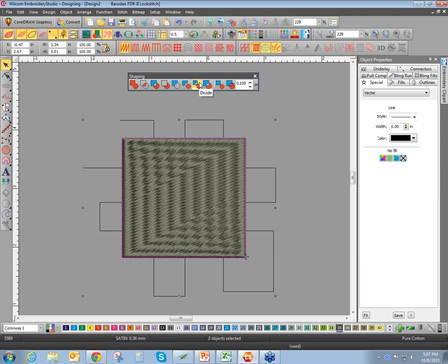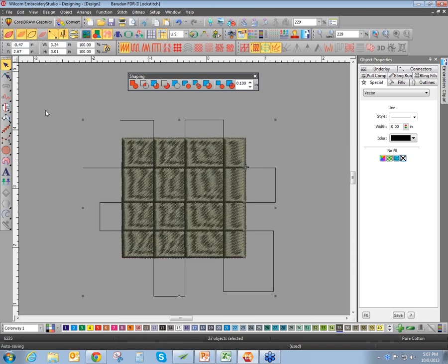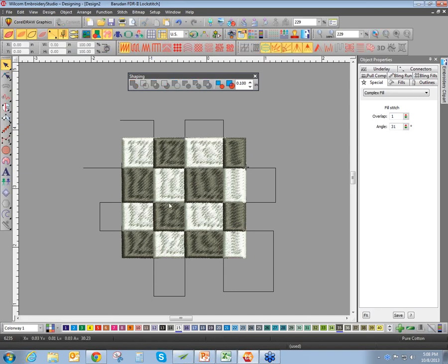I'm now going to utilize shaping tools. So coming back to that element, shaping tools, I'm going to create a division. Click divide, and it's now literally separated those fields. Click of a button. Again, you could have done that with running stitch, but you would have to go back and delete this running stitch. Drawing tools and vector lines allow you to do these types of creative effects without having to go back and delete that and manipulate that anytime.